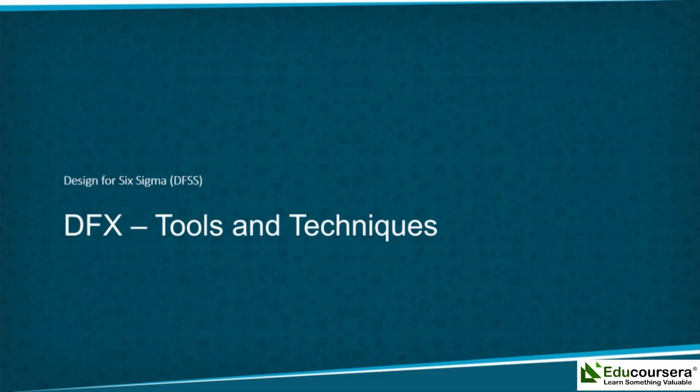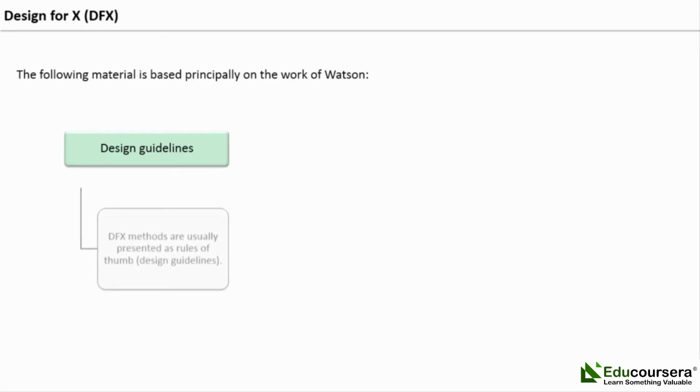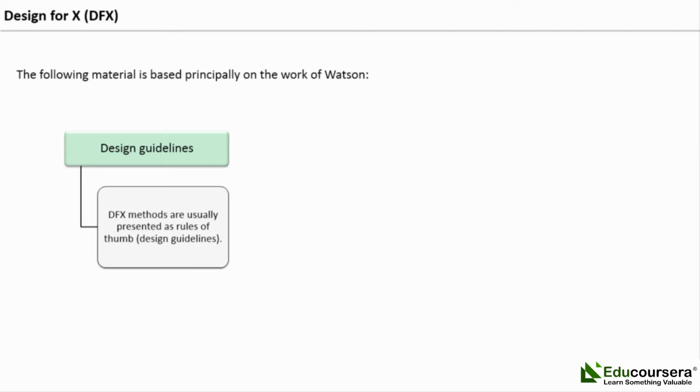DFX tools and techniques. Design for X, DFX. The following material is based principally on the work of Watson. Design guidelines. DFX methods are usually presented as rules of thumb, design guidelines. These rules of thumb provide broad design rules and strategies. The design rule to increase assembly efficiency requires a reduction in the part count and part types. The strategy would be to verify that each part is needed.